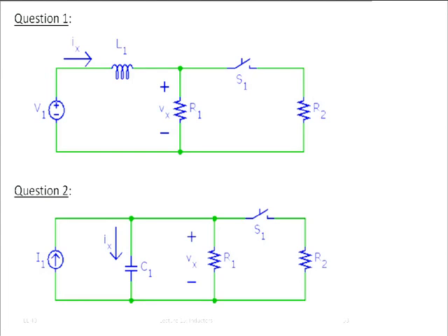We say, well, it's really this effect that matters most, and that we are most interested in. And then we can analyze it. That will usually be a first or second order circuit. And then afterwards you use SPICE, the circuit simulator, to verify. If the circuit simulator agrees with what we've calculated, then all these higher order terms really are not significant for our application. But of course they are there, and sometimes even SPICE has difficulty with really high order circuits, because what we really build is very complicated.